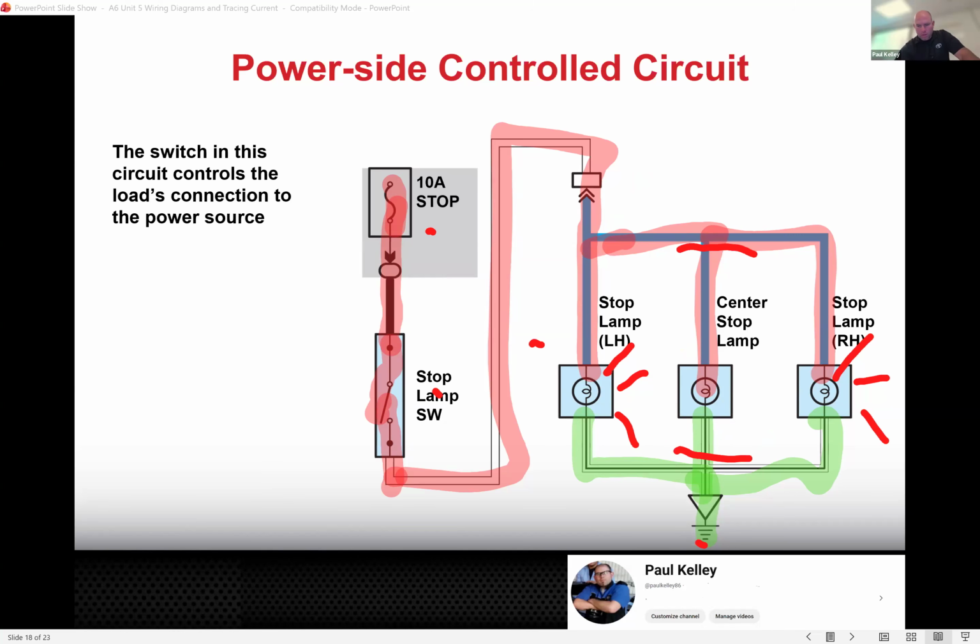So if this was a terminal 1 and this was a terminal 2, and let's say I got 0 on terminal 1, then what do I know? Let's say I got 0 right there. Then I know it's really between here and here because I'm not getting any 12 volts down there. Cool. So then basically that's it. If I know it's between this splice and this connector, that's as diagnosed as it needs to be. It's on that wire.